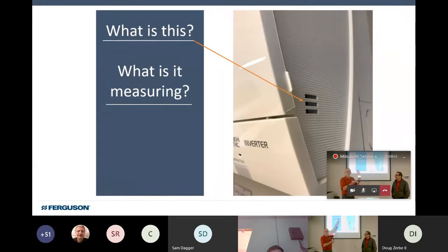It compensates for the height versus down where your customers are, but that's how you control the room temperature. So if you can't get air there, you're not going to have proper control. And especially if you're open to the outside air at that spot, you're bringing that outside air, whether it be cold or warm, across the sensor. In the wintertime, it's going to feel that cold air and it may overheat the space. Summertime, the opposite. Overcool.